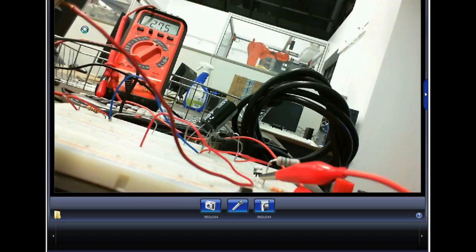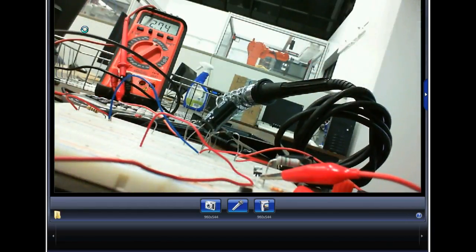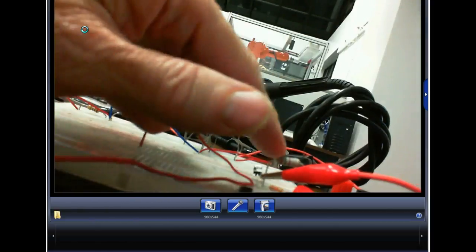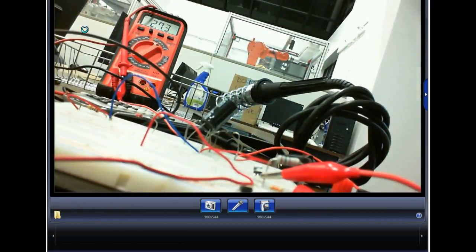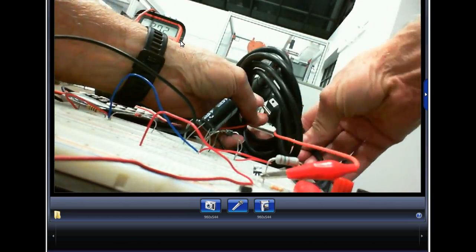And what did we do the other night? I got this device right here called a soldering iron, and when I heated it up, the voltage drop across the transistor went down. So if the voltage drop across the transistor is going down, then the voltage drop across this 150 ohm resistor is going up, right? So we were seeing the thermal effects of the bipolar transistor. Are we okay? So I'm going to plug in my soldering iron.